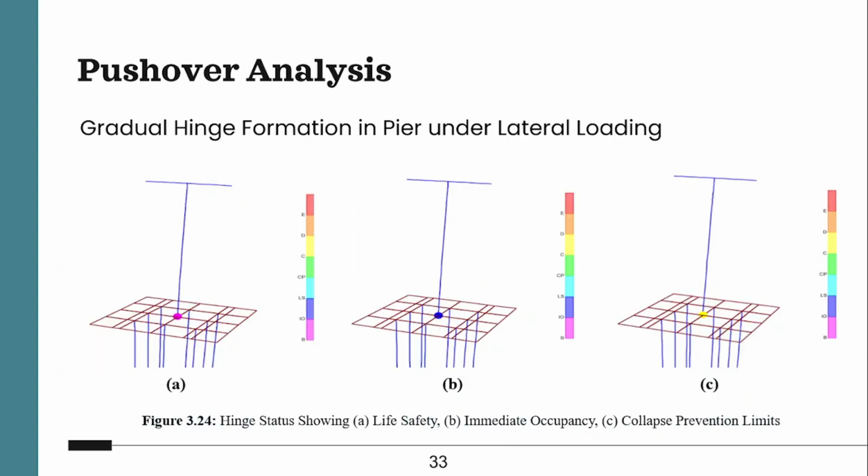Now we conduct a pushover analysis. For the pushover analysis, we first use a gravity nonlinear loading, and after that we assign the pushover analysis. In this pushover analysis, we provide an acceleration loading to simulate the earthquake behavior, but it will be a static load. As this is a static pushover analysis, the force will not vary. It will be the same level of force.